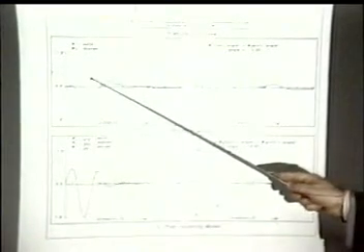Looking at the buckling modes, this is the one that has edge buckling. I mean, the big deformation of the buckling mode is close to the edge. Remember, this is not axisymmetric. It has n equal to 11, so it has 11 waves in the circumferential direction. But for most of the shell, you have nothing in the buckling mode. All deformation is concentrated there.